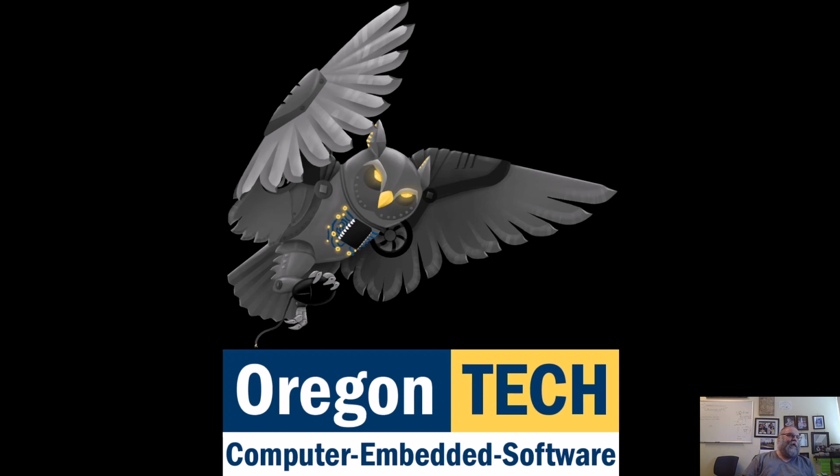So in today's video we are going to be taking a look at a tool that is built into Quartus. That tool is SignalTap. What SignalTap allows us to do is basically implement a small logic analyzer inside of our FPGA so that we can take a look at what's happening inside of the chip. Now we can use this with our FPGAs if we have enough spare resources, because this does require FPGA resources in order to implement it.